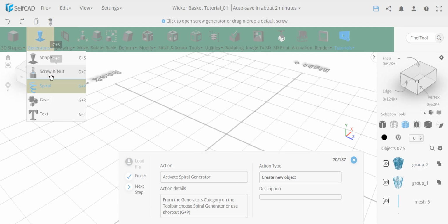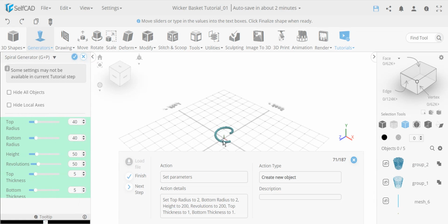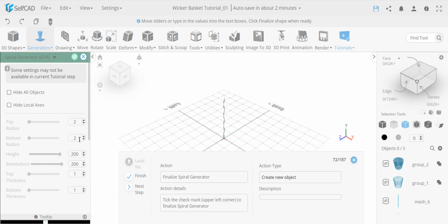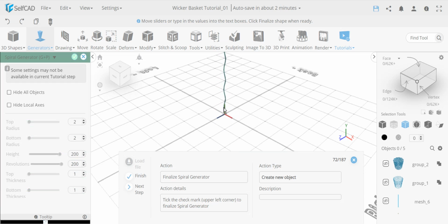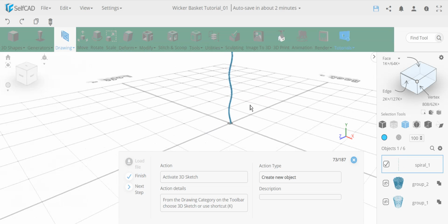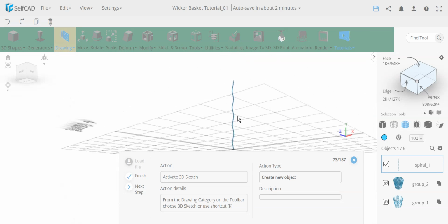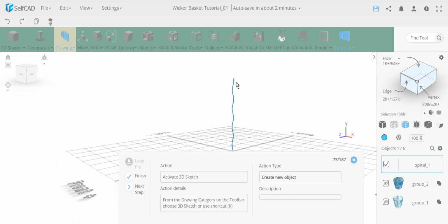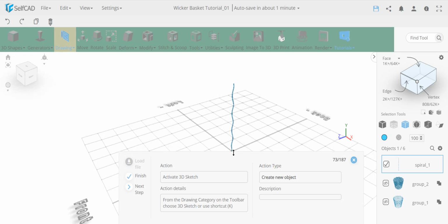So we're going to go now to the next. We create a spiral, which in this case is just another element. I'm just going to click next to all of the settings. It has a lot of settings. All it did is it took a spiral, and instead of keeping it as a spiral, it created a stretched thing to bend them. So instead of manually creating this as a spline, and then maybe using follow path to create this as a mesh, just use a spiral to do this.